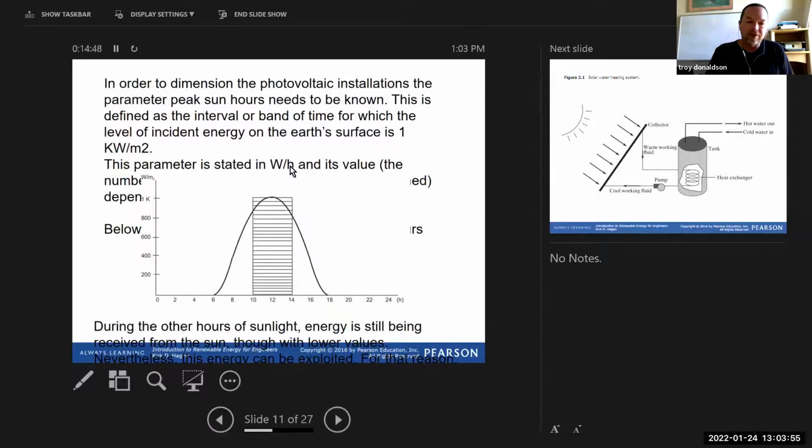All right, so let me just talk about the production of a solar panel a little bit. That's something you should know. And it doesn't happen throughout the day, right? We get the most production when the sun is perpendicular to the panel. So the panel gets set either for a winter set or a summer set or somewhere in between, if it's not adjustable. Now, there's a lot of adjustable systems out there now.